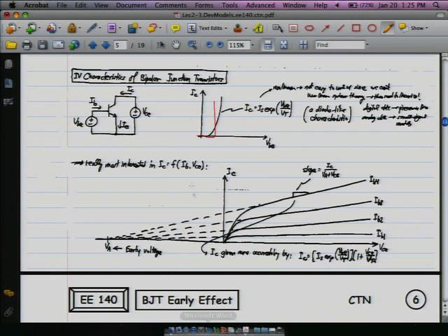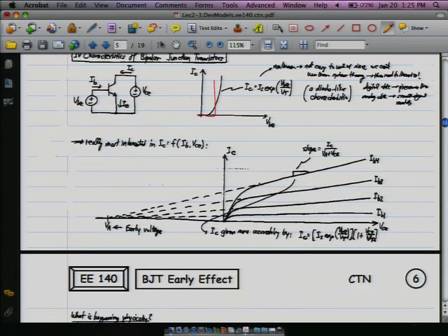We'll get a little bit more into where the small signal model comes from in a minute. Again, this is mostly review, but the thing here that we should know is we're most interested in the collector current as a function of the base current and VCE. So that's what we get here: these various steps up here are the base current, and VCE is what runs along this axis. And so those are how we're going to try and explain this.